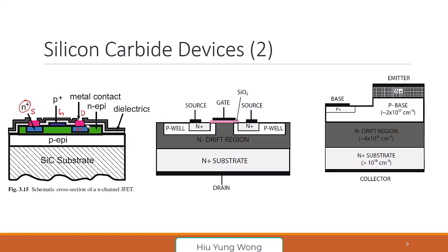In logic, for NMOS, the body is P-type. Do you see here? The green one is N, so there is no PN junction. So it is N-type. Then how are we going to turn it off? Because now this is just a simple resistor. This is something called a JFET, junction FET.